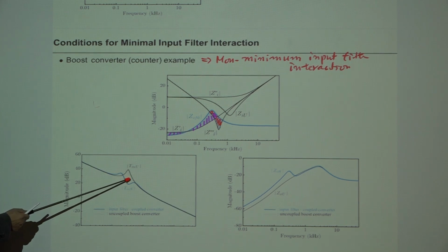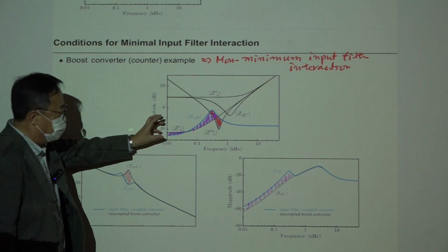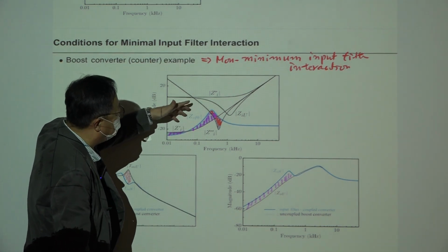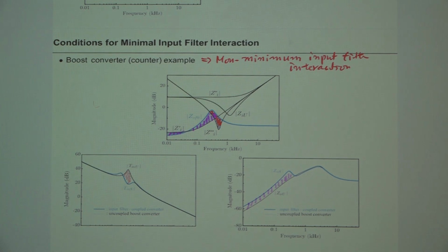So there is some variation, and I think I said this previously. This variation shown here is directly related to the overlap in this region, and the deviation here is related to the overlap in this region. This is another overlap, but we don't have enough separation here. Because of that and some phase characteristics of this, you have a boost of this much in output impedances. So this is the result.